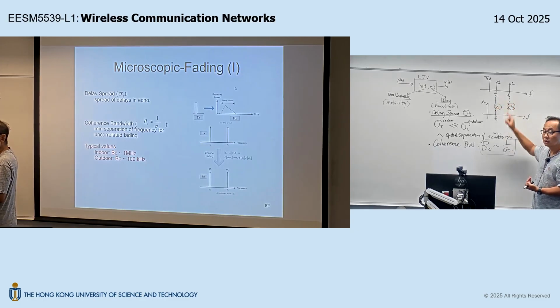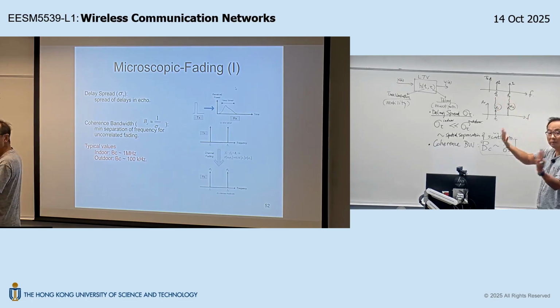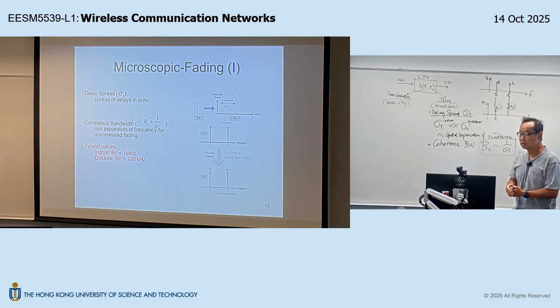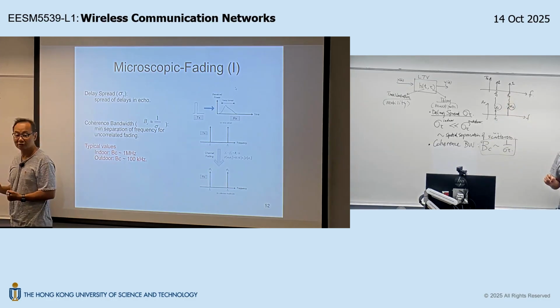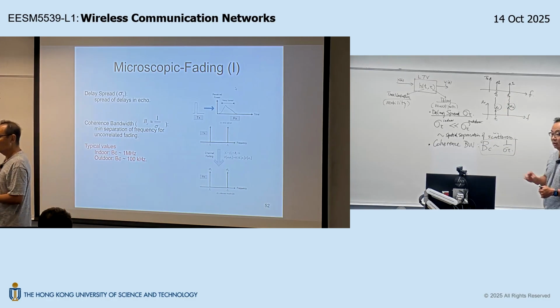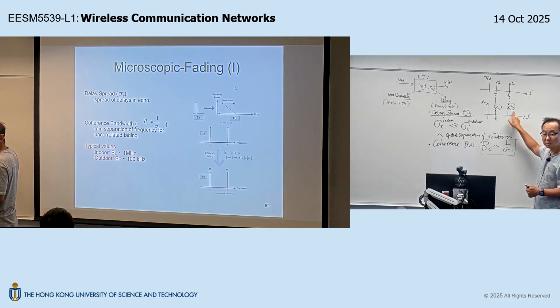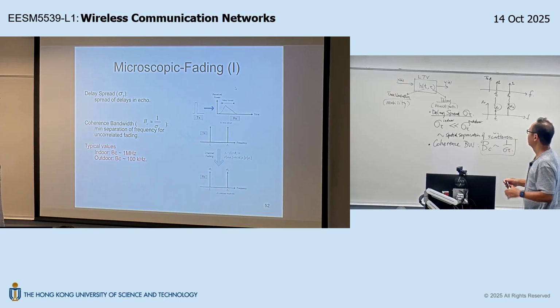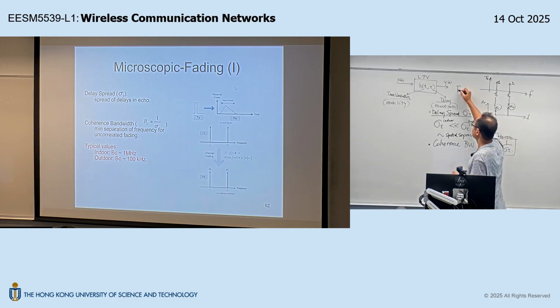Is that okay? So the response you get when you transmit a frequency F1 and the response for the same multipath, the response you get when you transmit at F2 may be different, okay? Because they have different wavelength in these two attempts. Is that okay? All right, with this understanding, so these are two random responses. When we talk about two random numbers, we can talk about a statistical measure called correlation. So we can talk about correlation. Correlation is the average of this alpha 1, alpha 2. Okay, this is called correlation.